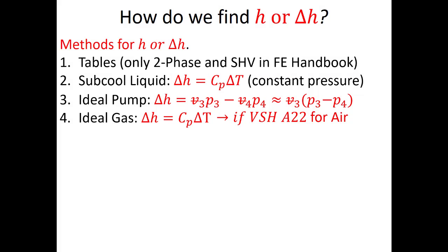Basically, anytime you write down an equation that has Cp, right? Two of these equations have Cp, or if they have Cv, like you might use Cv times delta T is delta U, or if they have the expression with k in it, right? So k is the specific heat ratio, Cp divided by Cv. Anytime you use those equations, you're making the assumption that the specific heat is constant. Otherwise, you would have to integrate over temperature as it changes. So if you write down those equations, but you don't tell me you're assuming that the specific heat is constant, then you're demonstrating to me that you don't understand why you're using those equations, right? So you have to tell me that specific heat is constant if you're writing down an equation that has specific heat in it.